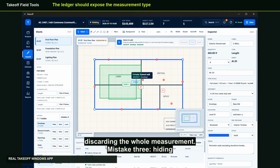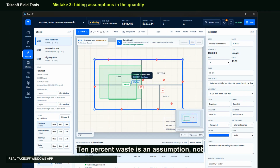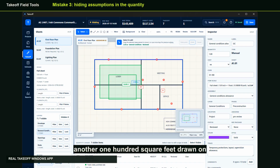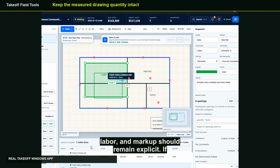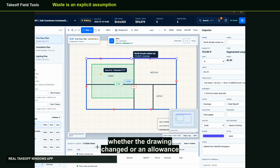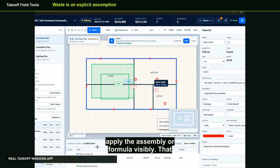Mistake 3. Hiding estimator decisions inside the measured quantity. The drawing may contain 1,000 square feet. 10% waste is an assumption, not another 100 square feet drawn on the plan. Coverage, waste, conversion, unit cost, labor, and markup should remain explicit. If the estimator simply replaces 1,000 with 1,100, the next reviewer cannot tell whether the drawing changed or an allowance was added. Preserve the measured quantity, then apply the assembly or formula visibly.